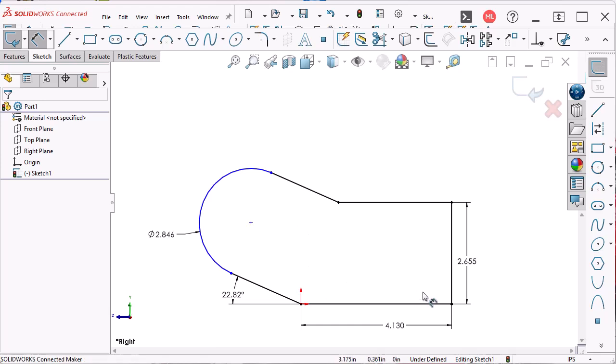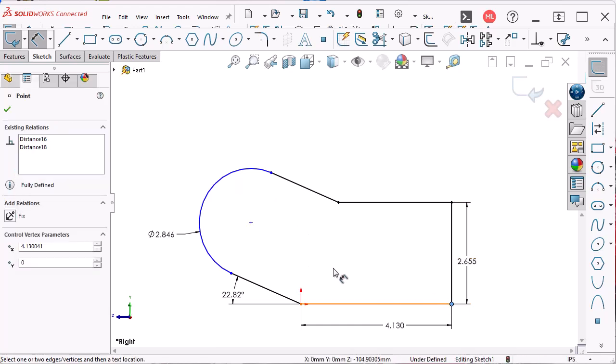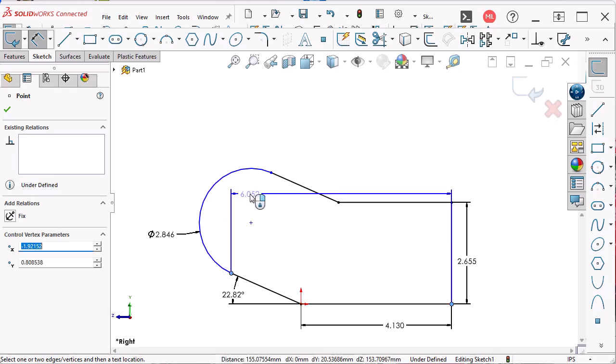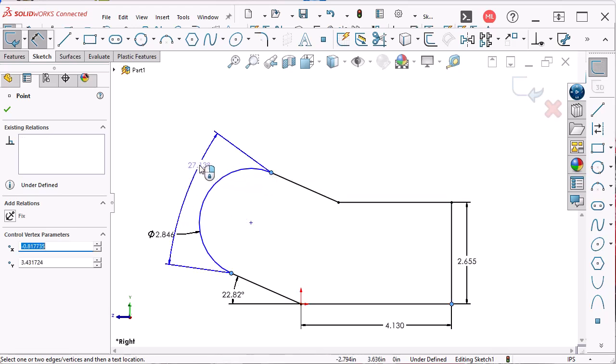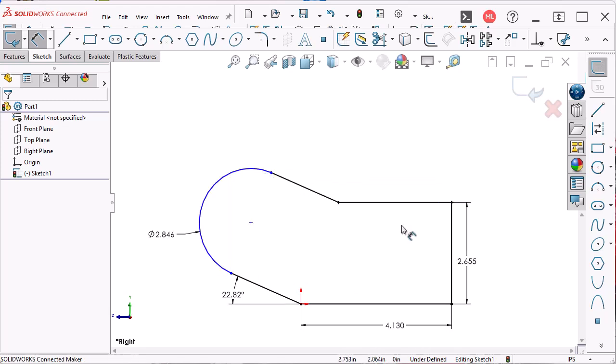You can go back and reselect all of the points for your angle dimension. But guess what? As long as you haven't placed that dimension yet, you can hit escape 4 times and it will unselect everything, and then the last escape will get you out of the dimension tool.